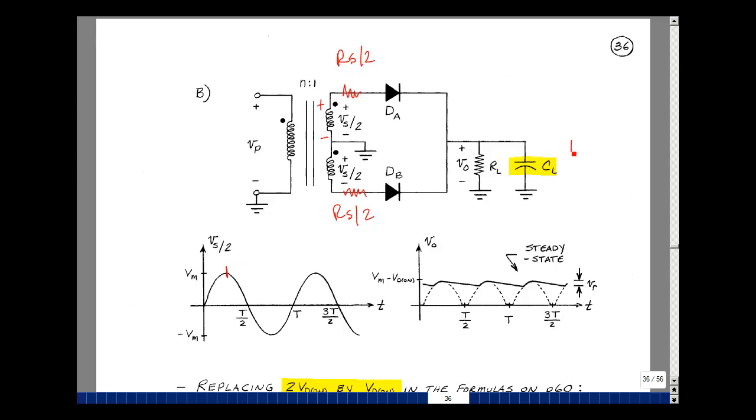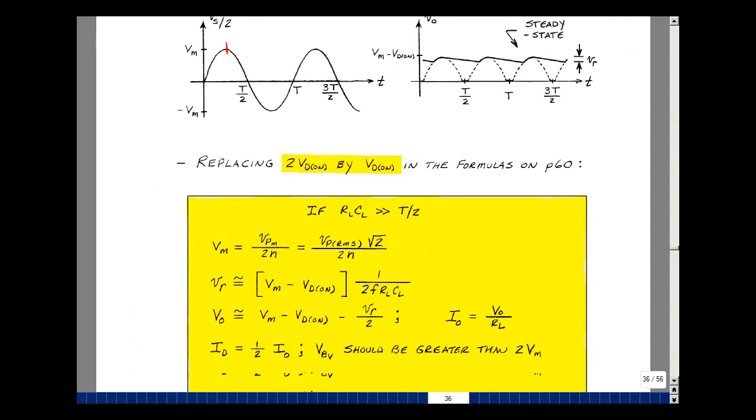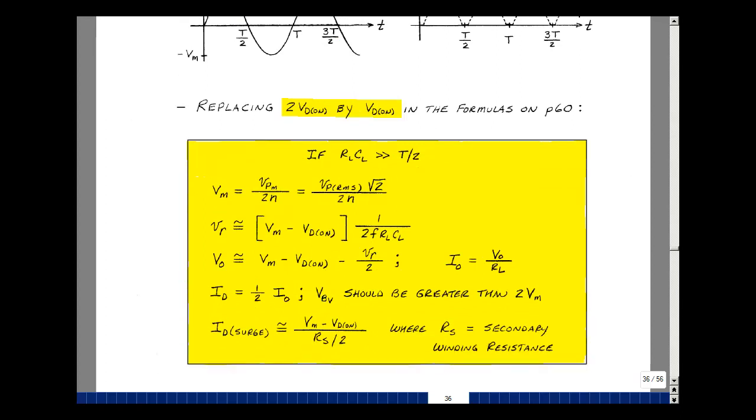That's going to be assuming that the voltage across here is 0. At this node voltage, which is V sub maximum, this is grounded. The voltage here is just going to be, if current flows, one diode drop. It's going to be V maximum minus one diode drop and then 0, and then dividing by the resistance. Same formula we had for the bridge rectifier, except that we have a 1 here instead of a 2. And this is supplemental problem 216.